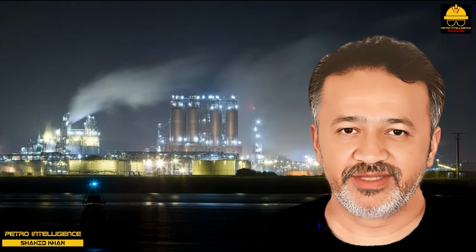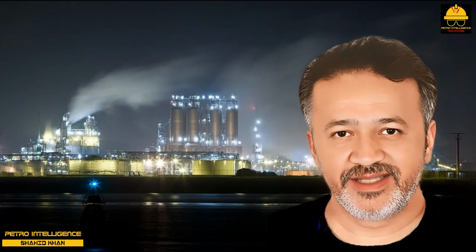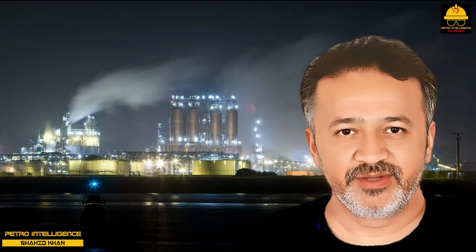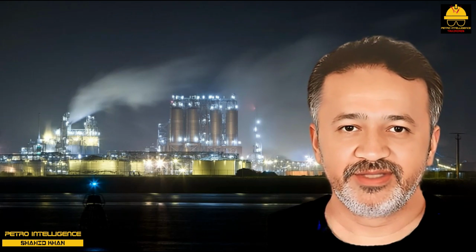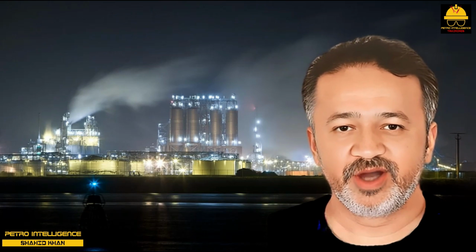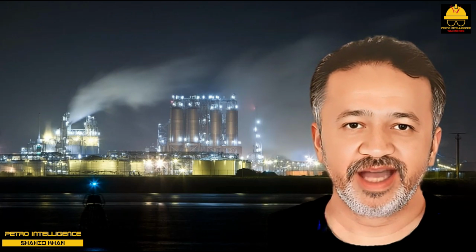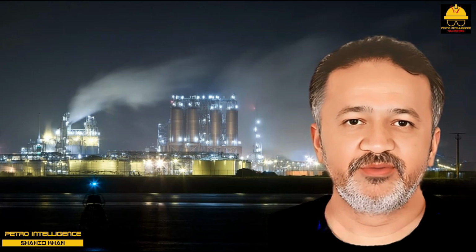3. A floating head bundle is designated as an AET pull-through floating head exchanger or AES floating head with a split ring backing device. This sort of a bundle has one fixed tube sheet and one floating tube sheet. One end is left free to float to accommodate the differential rate of thermal expansion between the shell side and the tube side. In this exchanger, the tubes are straight and can immediately be inspected to see if they have been properly cleaned. However, unlike the fixed tube sheet configuration, this floating head bundle is not a true countercurrent flow configuration. Hence, its LMTD must be reduced by the F-factor correction factor for non-true countercurrent flow.